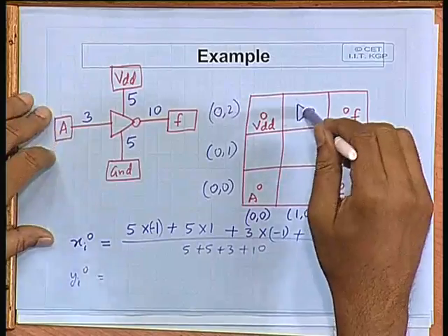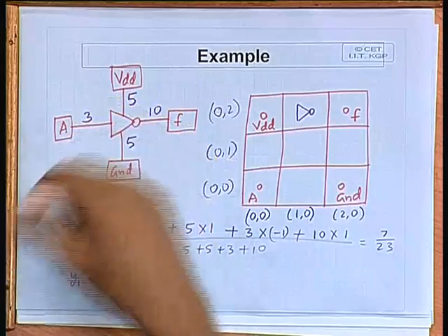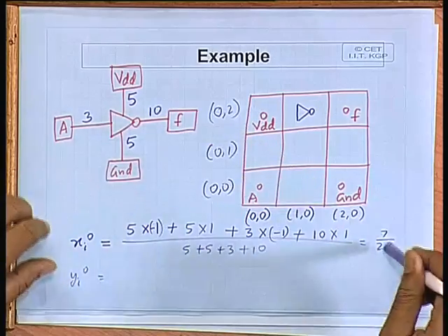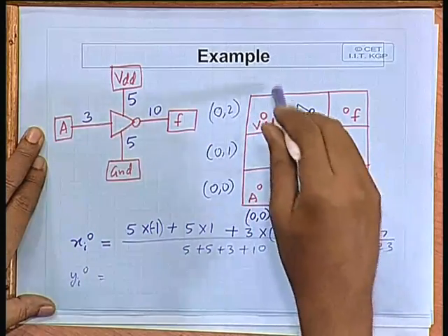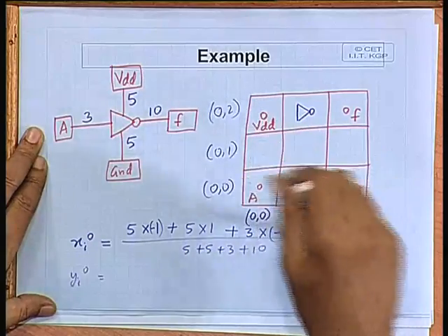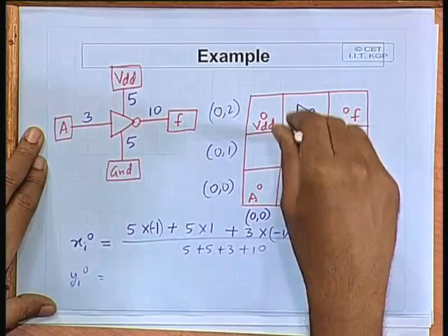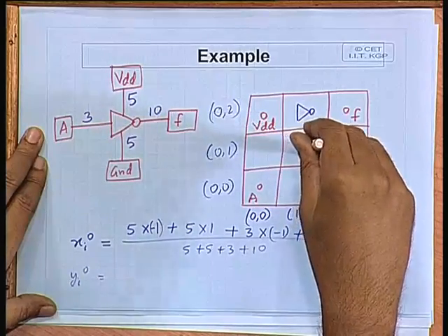But it is not necessary that if I place it at the nearest integer, that would give me some option. No, see, this is the zero force location. You try to place it as close to that position as you can. That is the idea, because you cannot place in a fractional place. It has to be aligned with the grid, because we are assuming some grid x y z x y. So you are approximating it to the nearest grid point and trying to place it there. Fine. So this is the essential idea behind constructive placement.